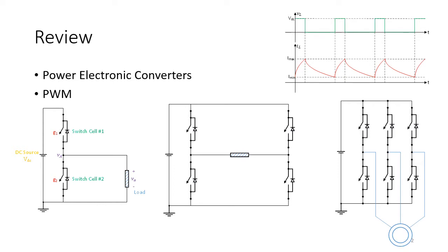We talked in detail about the half bridges and the PWM, how we change the width of the pulses while keeping the frequency constant, pulse width modulation, and how it impacts the currents, how they change exponentially, and when we can approximate them with a straight line instead of the exponential change. We were talking about the full bridge last week, when we almost ran out of time.